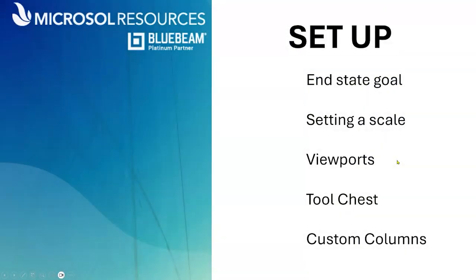So a little bit of setup. The first thing that we're going to go over is I'm going to show you guys the end state goal. What I mean by that is what a fully marked up document looks like with a bunch of different takeoffs and a lot of information on it. And then we'll kind of work backwards and then work up to that point, and I'll show you how we get there. And to start with that, you got to start by setting a scale on your documents.